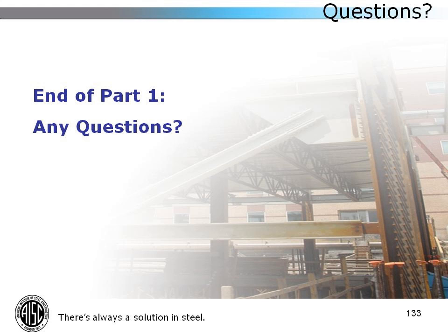We don't specify any such priming. It was done just based on the raw steel, which sometimes does have your oil film coat on it. So painting of the member probably really wouldn't have much of an effect on the low bond strength. Again, what you're going to see is that the bond strength is so low that you're really going to have to provide some sort of positive means of connection.